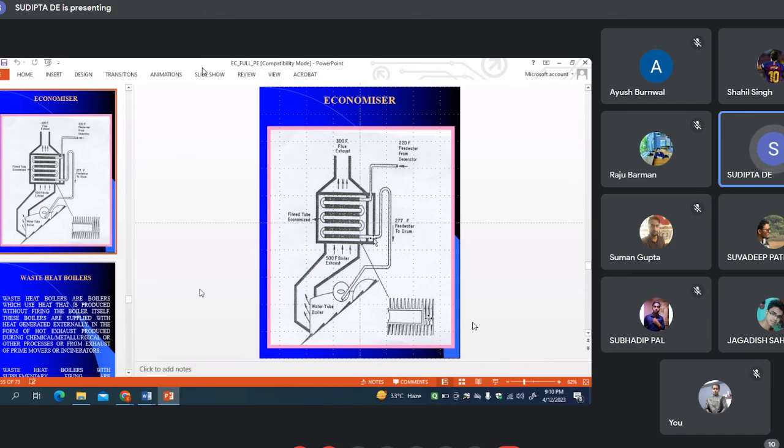What happens actually is that the liquid comes as feed water from the deaerator, which we also discussed during our CCGT cycle, and then goes into the drum. And obviously in this process there is another important issue you must remember. From the energy economics or better energy performance viewpoint, whatever the inlet water temperature may be, our desired temperature here is the saturation temperature, because subsequently it will enter the evaporation process.